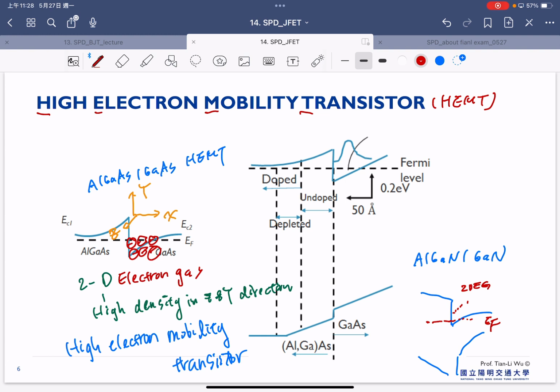And if you still remember, when we talked about the band diagram, there's a concept called degenerate. Once your Fermi energy is above your conduction band, we call this a degenerate semiconductor, because we consider that extremely high doping. It's a semiconductor like a metal.